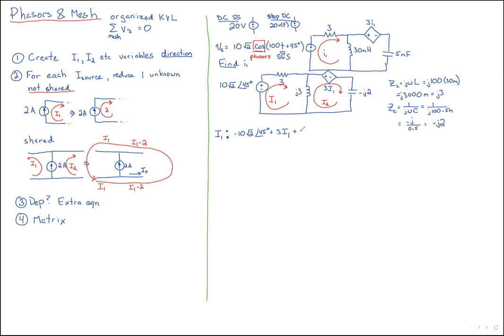Yeah, so this is going to be J3. And then my question for you, KC, is how much current do we have going down it? From this side, we've got I1. And how much current is going down it from I2? Would it be minus I2? That's it. Yeah. And that's the whole circle. That's the whole mesh. And so all that has to be equal to 0.